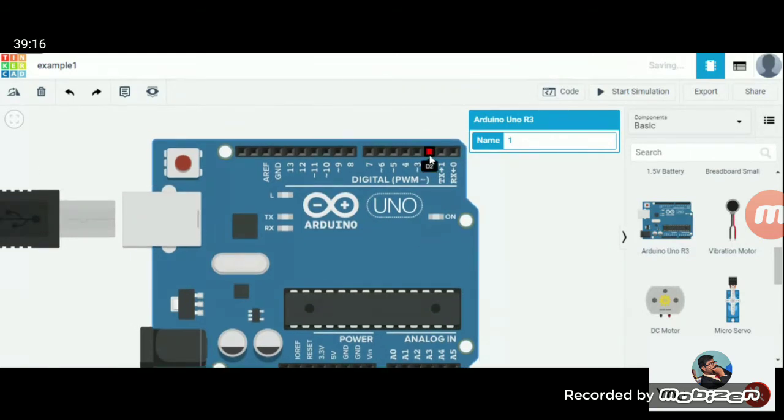So we can use the remaining pins. One more disadvantage with these microcontrollers is that they produce an output of very low current value. So we cannot drive switches directly. With respect to power electronics, you are mostly electrical students.